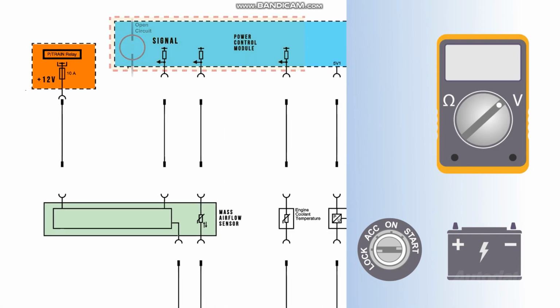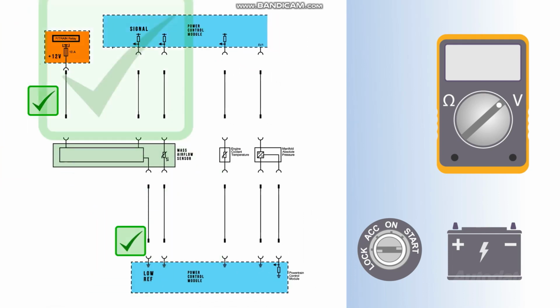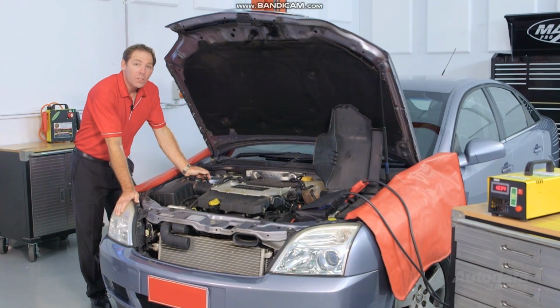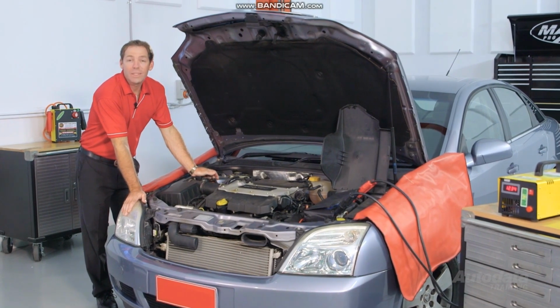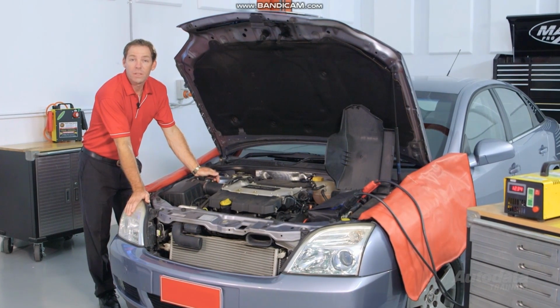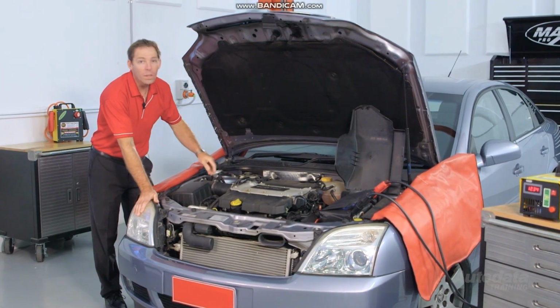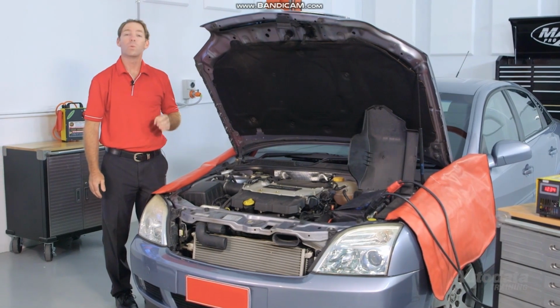If you have proved the high reference, low reference and signal circuits are okay, then the fault must be in the sensor itself. Diagnosing MAF circuit faults doesn't have to be hard. Take your time, understand the system you're working on. Training now will prepare you for the future.